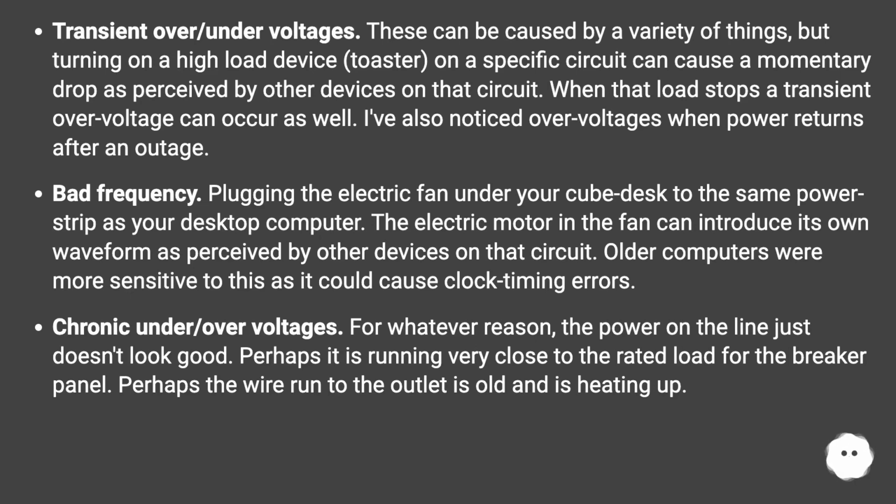Bad frequency. Plugging the electric fan under your cube desk into the same power strip as your desktop computer. The electric motor in the fan can introduce its own waveform as perceived by other devices on that circuit. Older computers were more sensitive to this as it could cause clock timing errors.